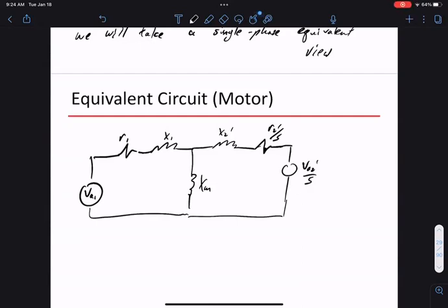All right, so if it is a motor, then the way power flows is in this direction. And if you're a motor, S is (omega S minus omega) over omega S, and this is bigger than 0. So that's why it's a motor. You have net power flowing left to right.